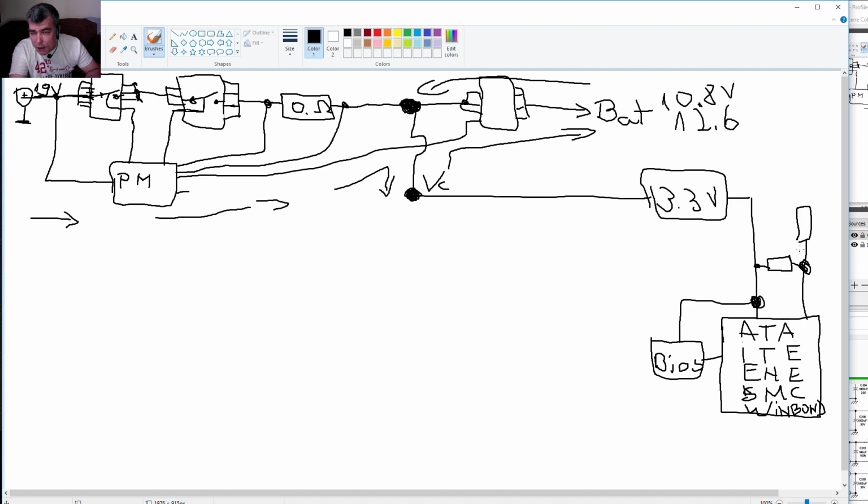So this resistor is keeping this pin always on 3.3 volts. The condition for this chip to start is this pin to be at ground, to move the 3.3 to ground. So here you have the power button, exactly this way. That's a switch, that's the power button, and this is to ground.